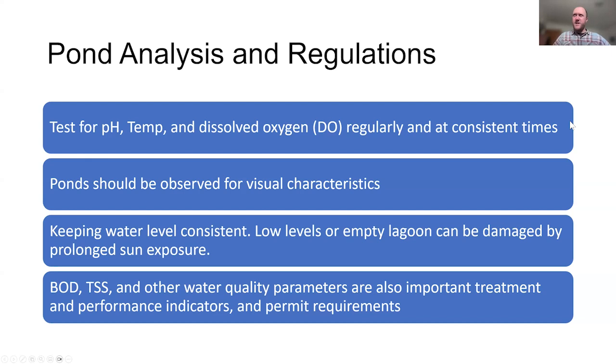Yeah, I think I was just discussing that. I think they're two pretty different processes. A constructed wetland would be a different scenario and would be made especially for that. In a lagoon, you don't necessarily want that because of the liner. I think you're going to have a lot more seepage. And I think constructed wetlands are a little bit more for polishing after another treatment process.